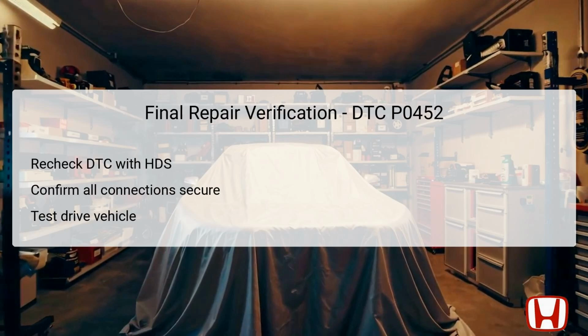After completing the necessary repairs or sensor replacements indicated by previous diagnostic steps, it's crucial to conduct a final verification process. Start by rechecking for any DTCs using the HDS to ensure that DTC P0452 no longer appears. If all systems are operating correctly, the DTC should be absent. Additionally, make sure that all electrical connections, especially at the FTP sensor and PCM, are secure and corrosion-free, as loose connections can lead to recurring issues.